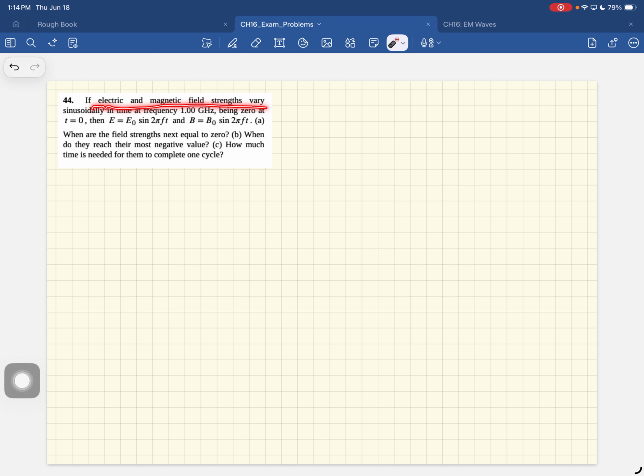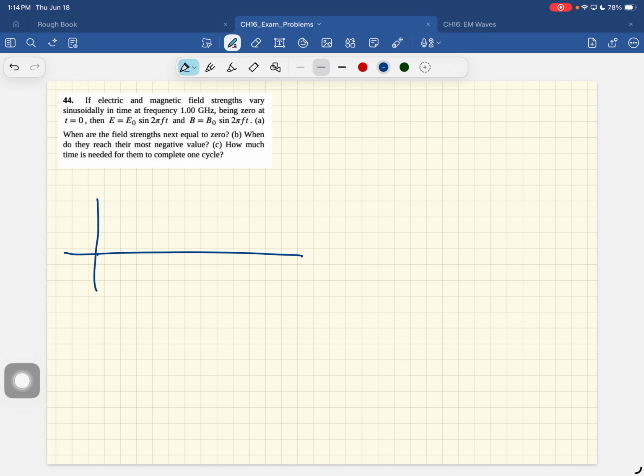So, what's the problem with the ring antenna? If you want to detect Orlando, the plane of the ring has to point to Orlando. If it's like that, your signal strength is weaker. But with the antenna like that, you don't care if you're detecting Orlando or Melbourne. This can point like that. So with the ring antenna, if you want to detect Orlando, you got to point like this. And if you want to detect Melbourne, you got to turn it like that.